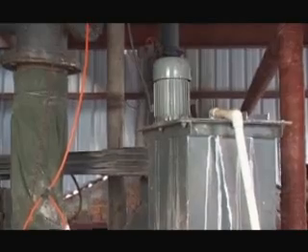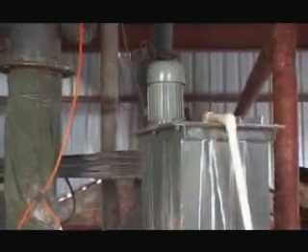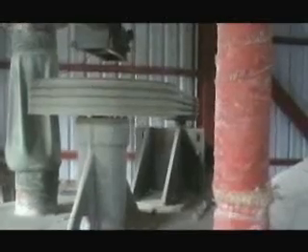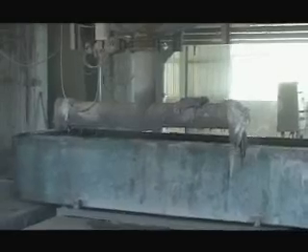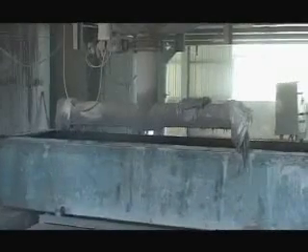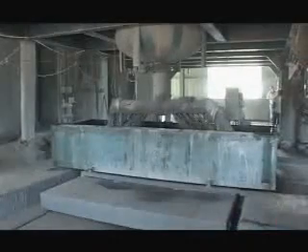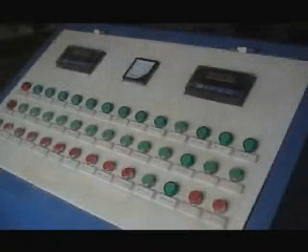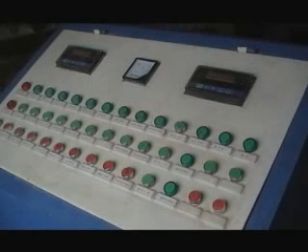After dosing, the materials are put into the pouring mixer for even mixing. The aluminum is added into the pouring mixer finally. Before pouring, the molds are transferred under the pouring mixer by ferry cart. The pouring mixer begins pouring. The whole process is controlled by the centralized control system to ensure the accuracy and continuity of dosing and the quality of AAC as well.